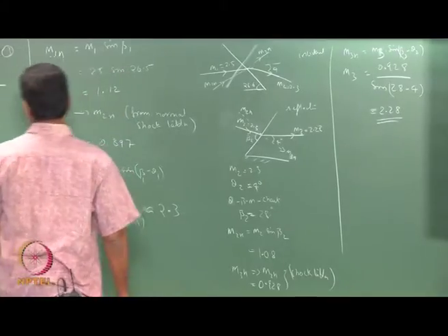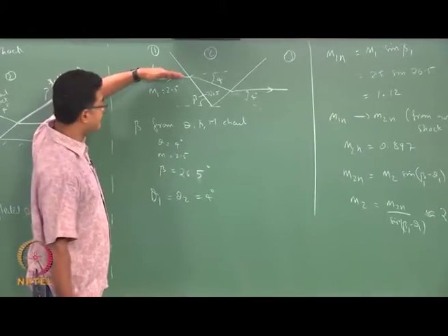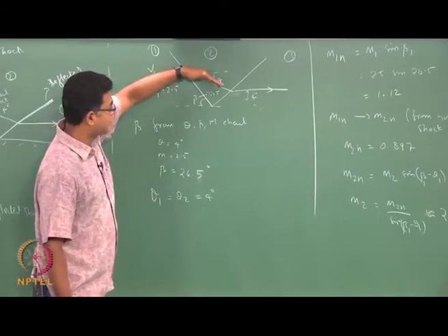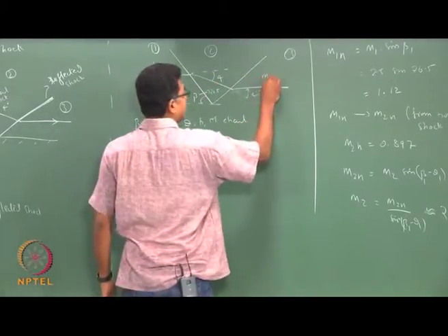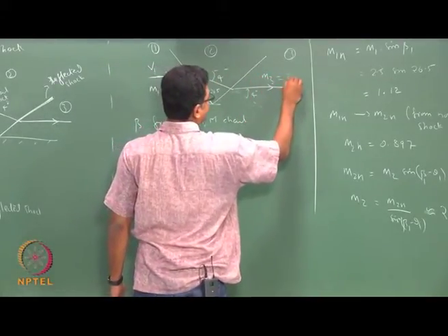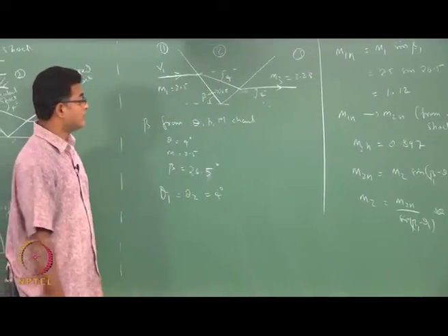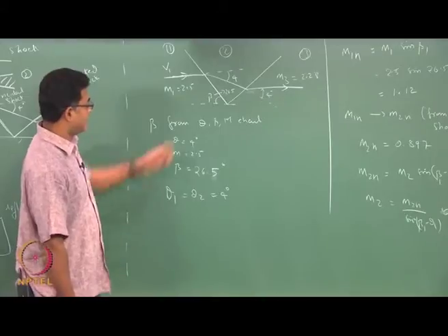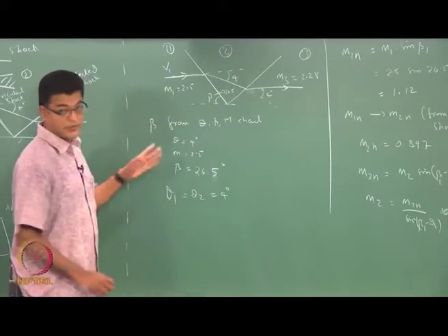Okay. So, from the problem, if you look at it, I have M1 is 2.5, which turns by 4 degrees and then turns again to M3. M3 is calculated to be 2.28. If you know these values M1, M2 and M3, you can find the corresponding pressure ratios.